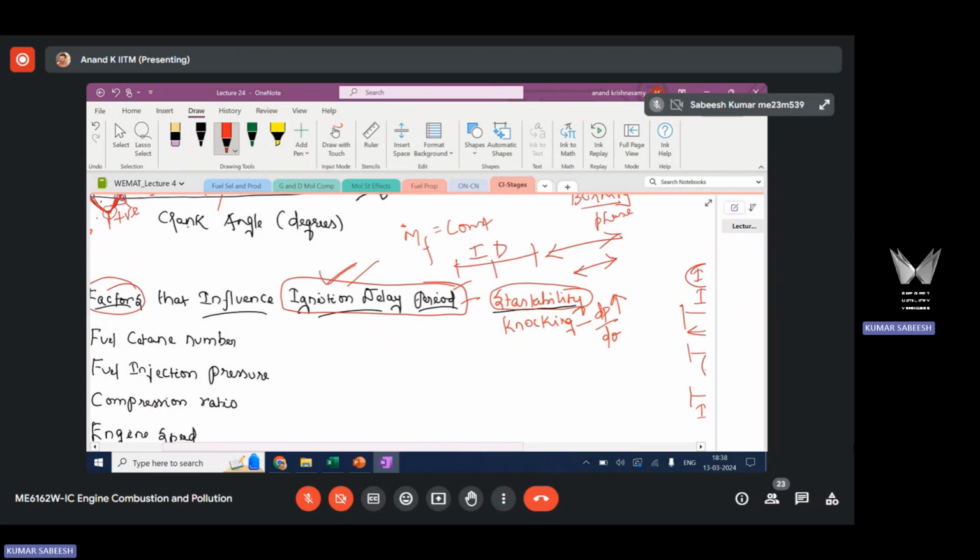So you have to ensure that you are controlling this delay time so that the engine is able to start. That's where cetane number plays a significant role. You need to ensure that fuel has the required ignition quality defined by cetane number. We have seen in chapter 1 that there is a minimum cetane number the fuel should have. Otherwise, the engine cannot even start. So ignition quality will play a significant role in affecting the delay time. This is one major effect.